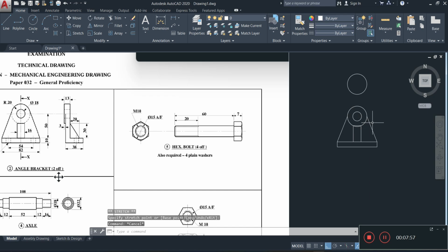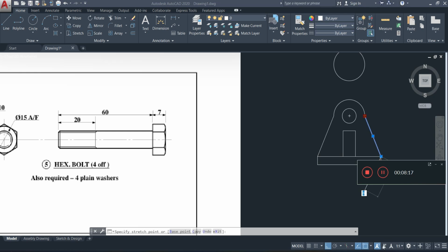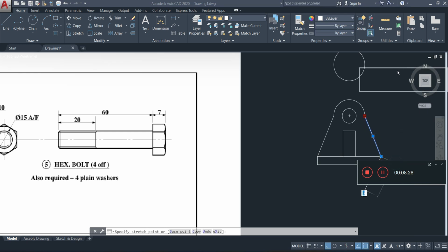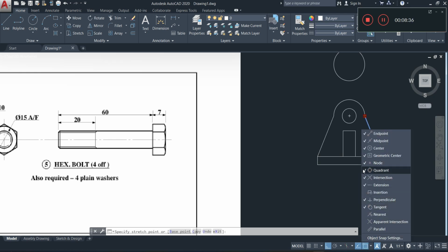Alright, so let's trim away this bottom portion using these two lines as my cutting plane, and then remove here. Then after, these are not at the right position, let's move them to a tangential point on this thing here. Let me move this out of the way. Snap feature, tangent, yes, it's on. Snap feature. I'm going to have some conflict if I don't turn off quadrant.